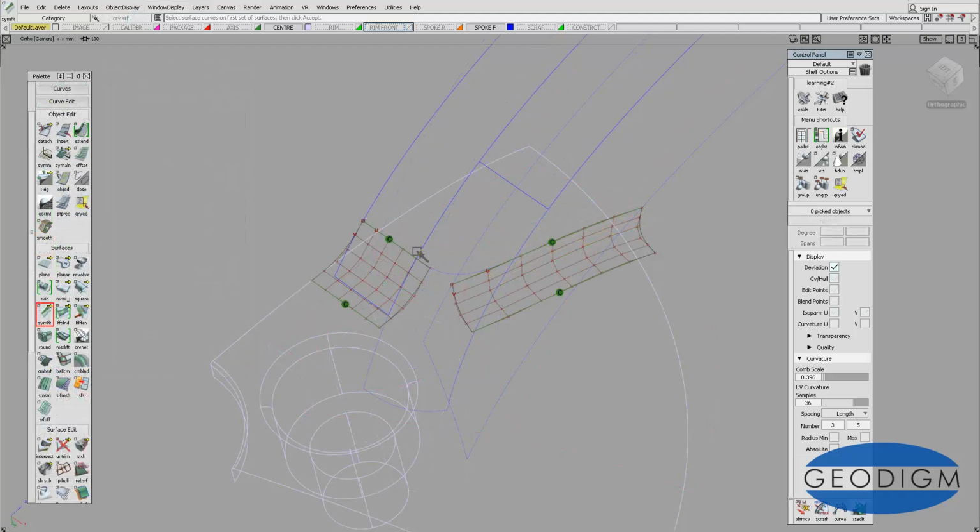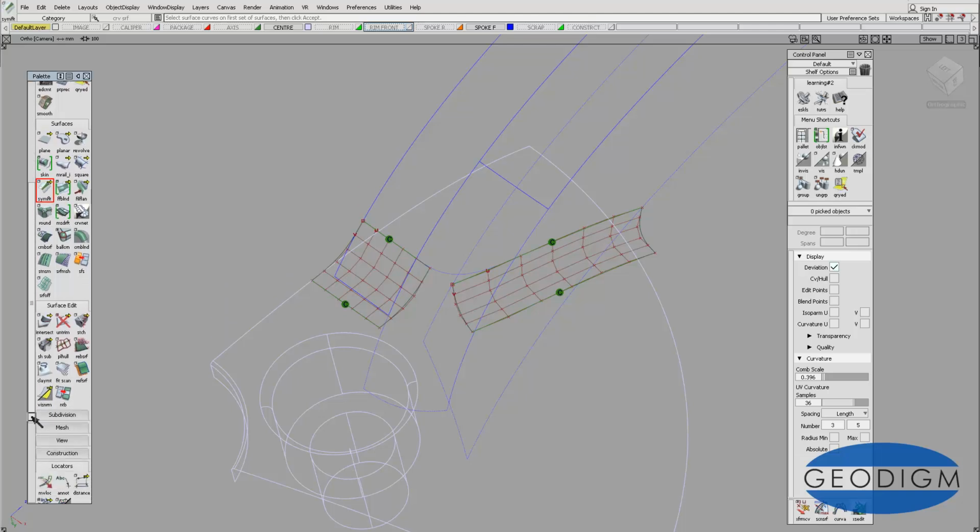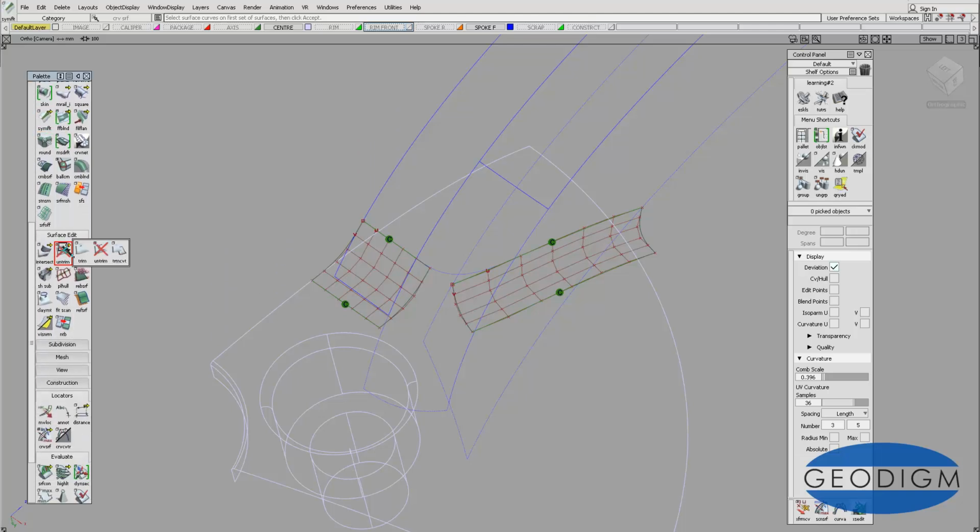Now we're going to trim back this surface here. We're going to trim it back, but we're also going to do a trim convert version of that trimmed surface. And the reason for doing that is that the trim convert version we can use for construction, and the original trim part we'll keep for our final model, so that we can always get back to this original fillet if we want to. So let's go into trim. This is a technique that I use on a lot of fillets.